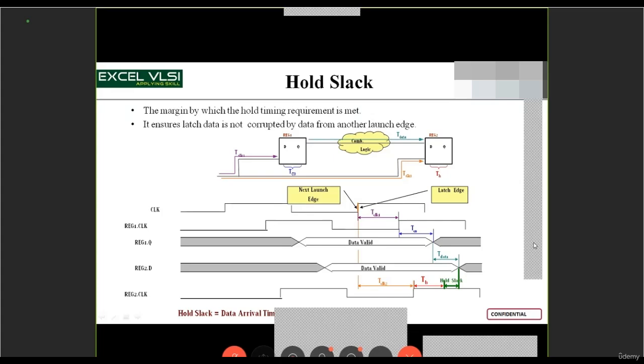you will get to know from experience itself that in the later stages this can get optimized. But out of 300 paths, if 240 or 250 paths are getting violated, it is difficult in the later stages to optimize that huge number of timing paths. That analysis you will get by experience only, while doing the iterative process. So in the pre-layout stage, yes, you will have some margin to move forward to the physical design.